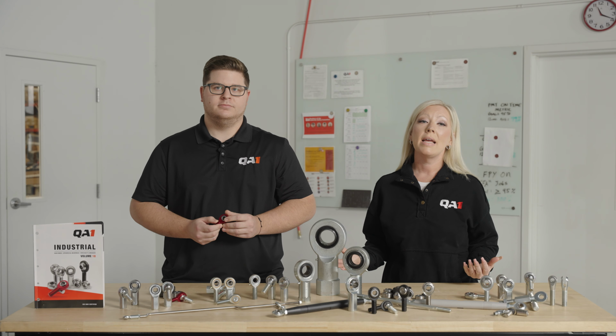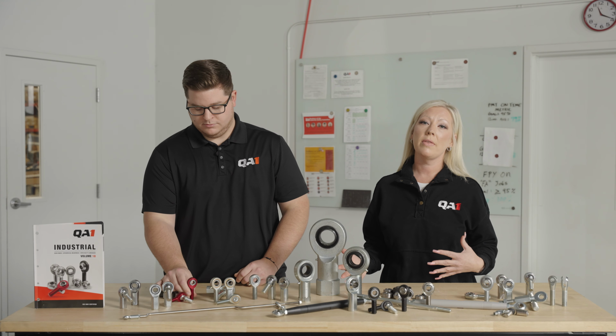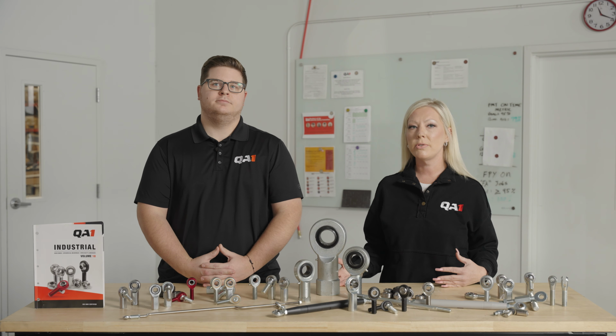Now that we've wrapped up rod ends, here are some quick rules of thumb to consider for choosing the right solution. For heavy-duty applications, you might start by considering loader slot or the alloy steel three-piece rod ends. For precision applications, think the three-piece rod end again, or maybe one of our self-lubricating options. And for cost-sensitive projects, consider a two-piece rod end. Now, let's shift to spherical bearings.